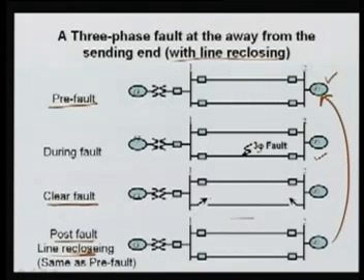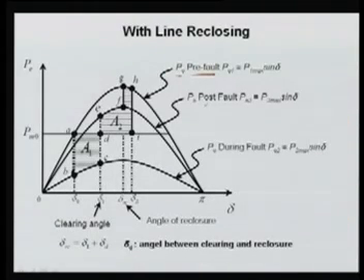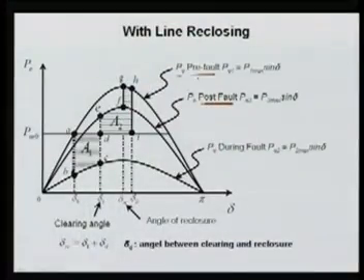So just we have here this curve, which is basically the fault cleared. At that time the fault is clear, but it is not a post fault. Post fault is again this condition, where it follows the same PE. So in this case your operation is at point A. Again it is an intersection of PM naught and the PE angle, that is the pre-fault, and after that there is some fault.